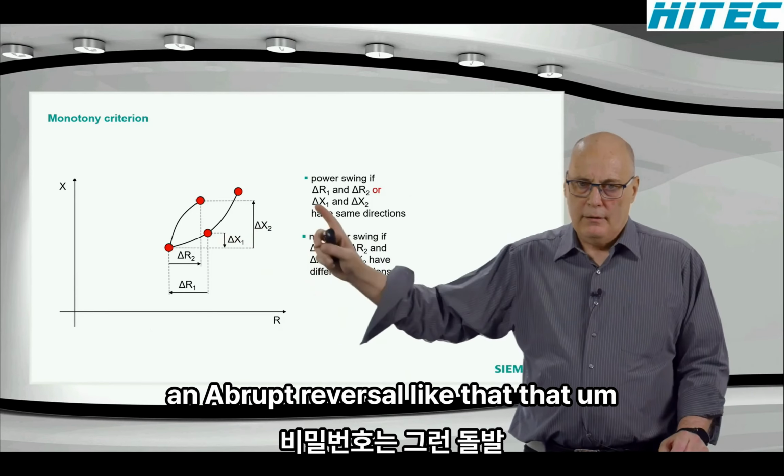There is no jump in there. It is like moving along a fairly complex path, the 3 machines swinging, but there are no jumps. This is just a continuous power swing. No fault or anything, it's just a power swing. And the advantage is obviously that the older, historic way of measuring power swings was using blinders, and this was just to show that with the blinder technique, it's difficult.